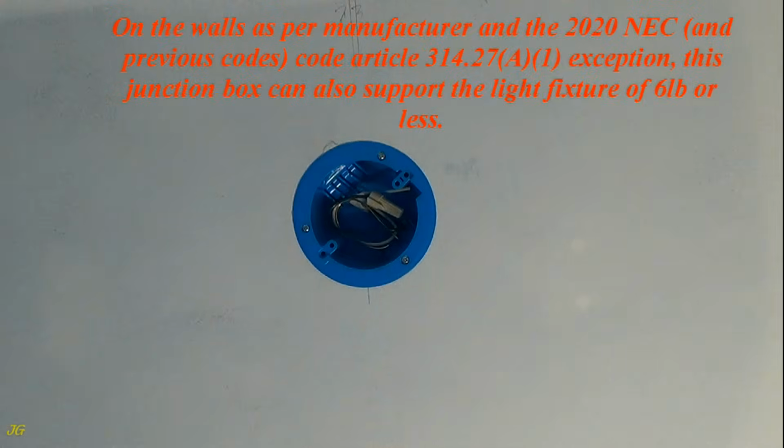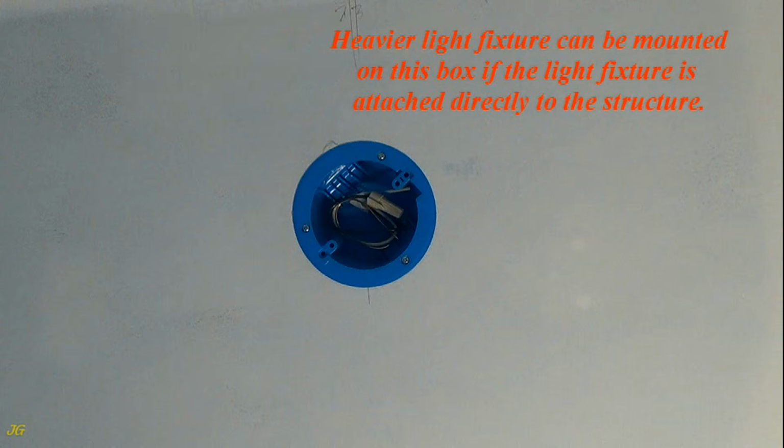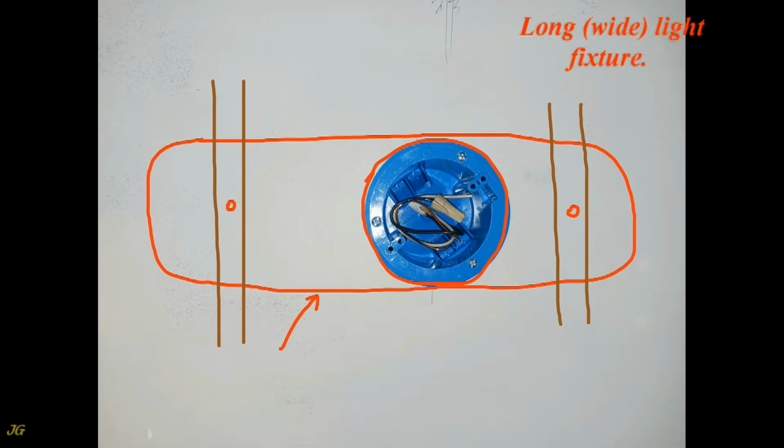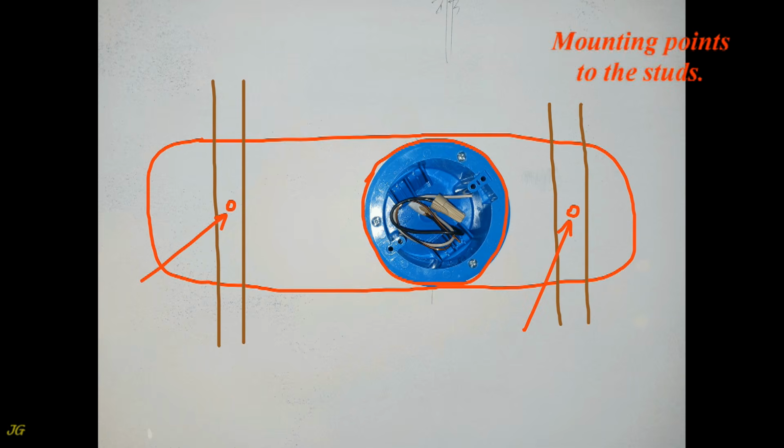On the walls, as per the manufacturer and the 2020 NEC and previous codes, Code Article 314.27, exception 1, this junction box can also support a light fixture of 6 pounds or less. A heavier light fixture can be mounted on this box if the light fixture is attached directly to the structure. Long light fixture. Light fixture connection. Studs under the sheetrock. Mounting points to the studs.